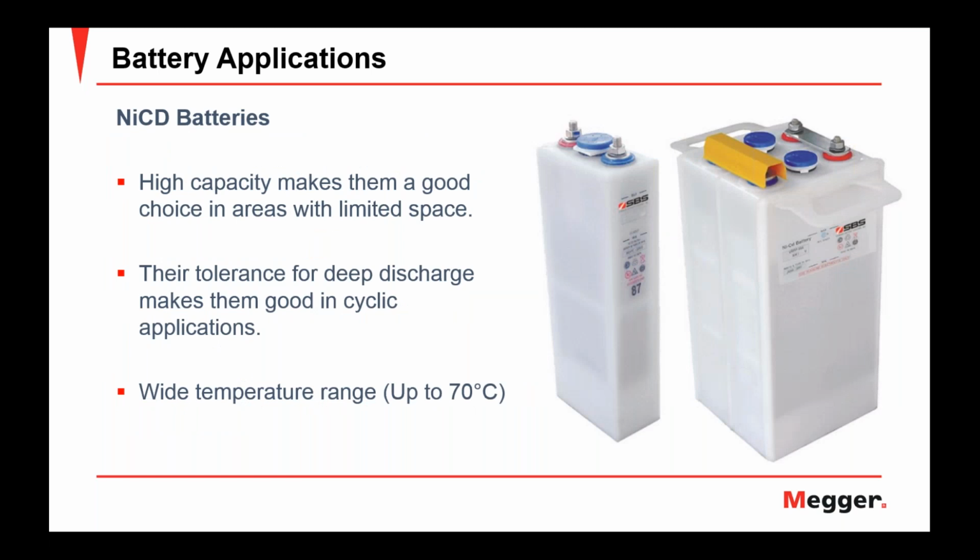So, NiCad batteries. NiCad batteries have a higher energy density than lead acid. So where you have limited space, these are a good choice. They're also very tolerant of deep discharge. Now, as I said, lead acid batteries and lithium ion can be damaged if they get discharged too low. NiCad batteries can handle being discharged almost all the way down to zero. You just want to be careful you don't reverse the polarity of them.